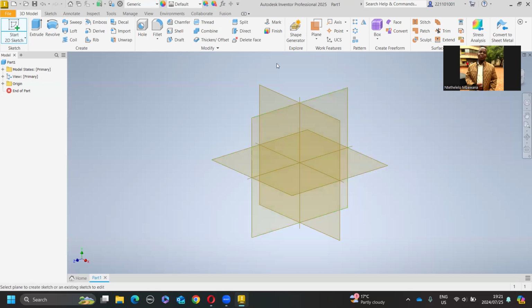If you look at your bottom left corner there, we can do something on the XY plane and extrude it towards the Z. Most of the objects that you can draw on the XY plane are objects where you'll be starting with the front side, okay?